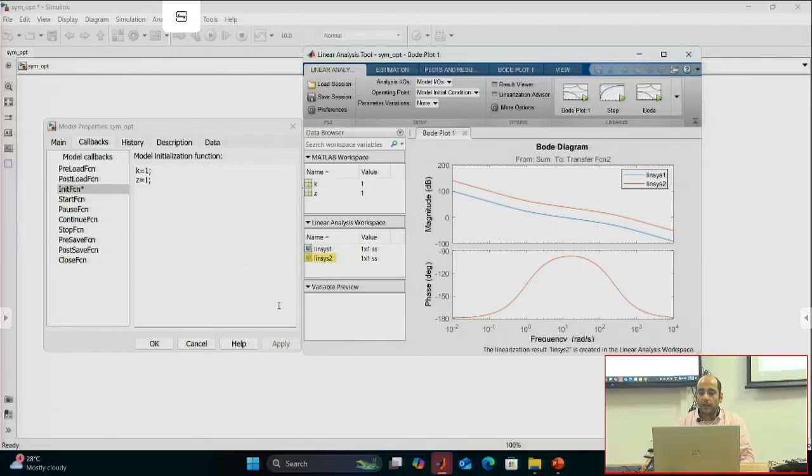If you change the variable z, let's say from 1 I make it 5 now, again I plot the Bode plot. You see what has happened. In the initial part there is some change in the gain plot, it's not much, but the significant change is this: the point where the maximum phase was obtained has shifted to the right side.